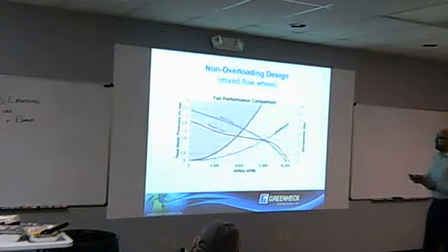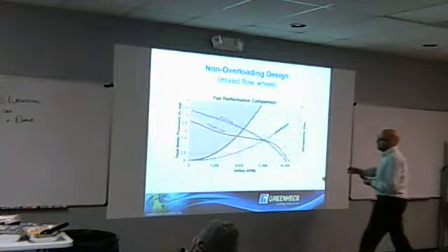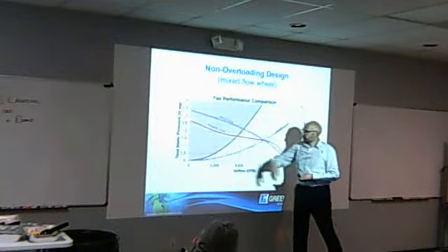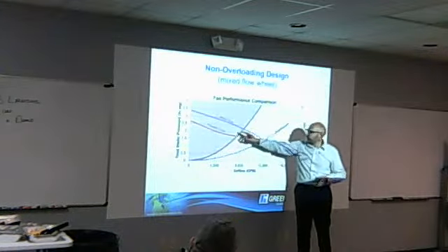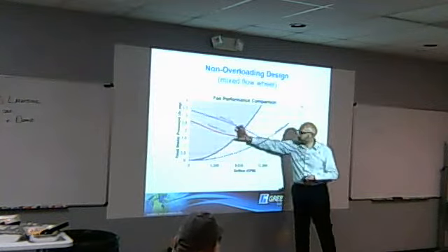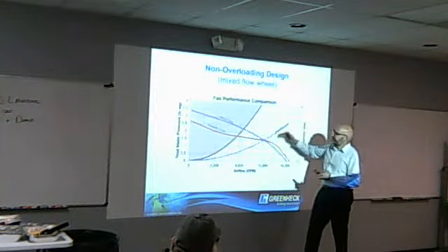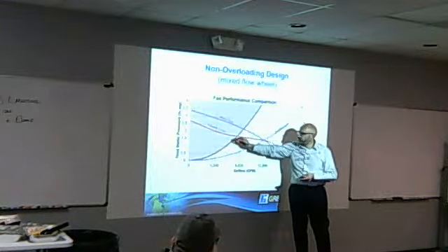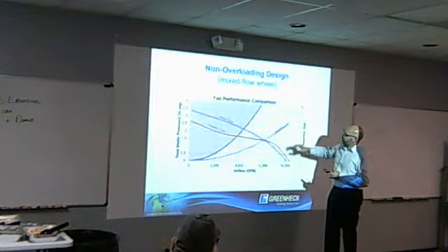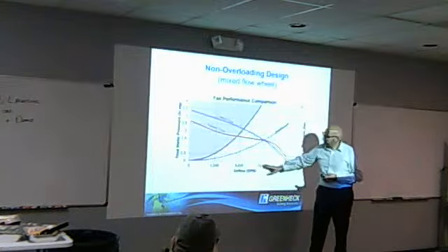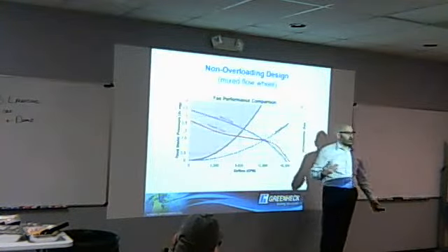So, we're going to look at a comparison of a mixed flow wheel and a forward curve wheel. This is the RPM line, and it can be arbitrary, but of the mixed flow and the forward curve. When we think back to that previous slide, if this was 1100 RPM and this was 1200, it doesn't really matter the value. The system curve defines the CFM and the static pressure we're operating against.